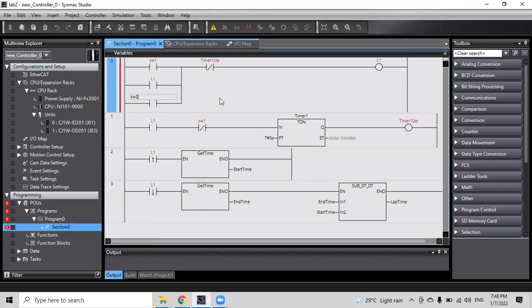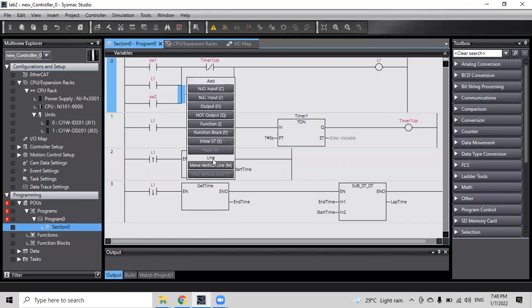Okay. So once you add this one, we can see here it is connected to the wrong place, because this one is supposed to be at the end of the timer 1 up, right? So what you should do? You highlight this one, and then mouse left button, click and hold. Go here. Okay, and then release. So now you can see a pop-up window.